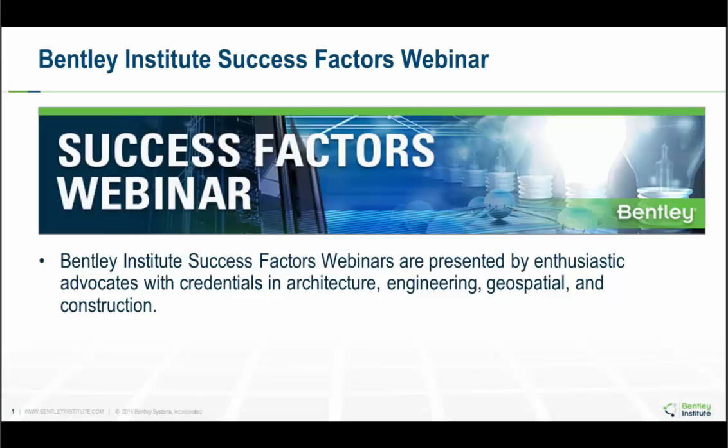Because the pushover analysis is in and of itself an iterative analysis, I believe that just by the nature of the pushover analysis the P delta effects would be accounted for automatically by the analysis.